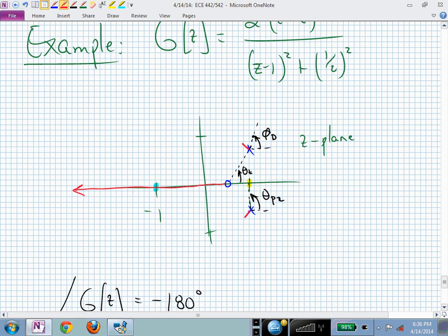This only works when you have two poles and a zero. If you had another pole somewhere or another zero, don't be doing this. If you had other singularities around, and let's say you still had this segment from 1/2 to minus infinity in play, could you find any more information on that z-plane that would help you?